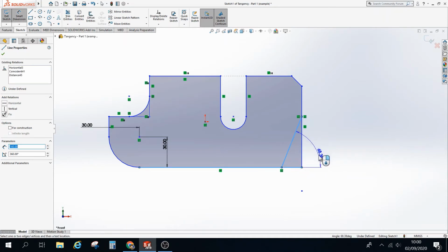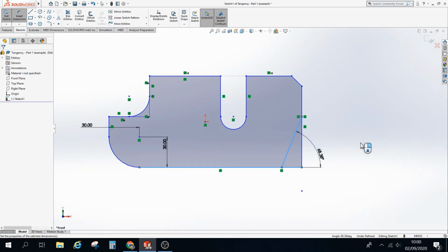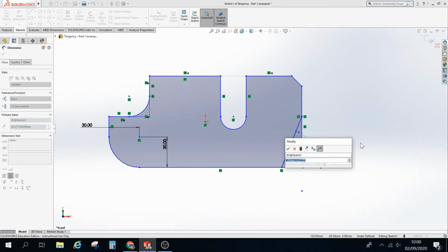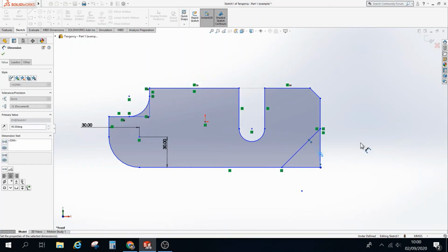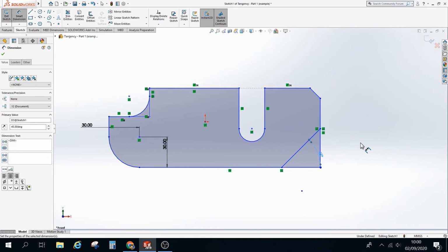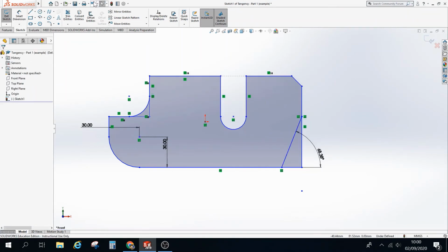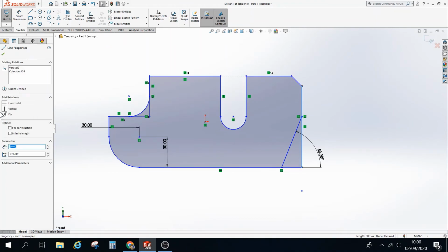The reason I wanted to go through this wee step is because sometimes when you adjust sizes, it can affect other elements on the page or other parts of the sketch that you're creating. So let's see what happens when we do this. You'll notice that the whole sketch has reduced in height. We don't want that, so there's a way to get around that. I'm going to select this vertical line and fix it in place so that that line cannot move.